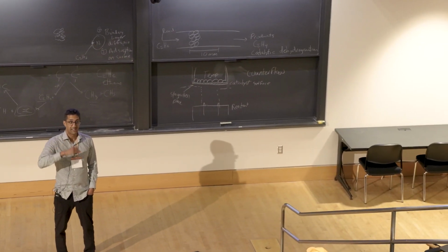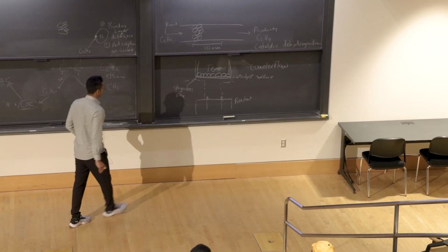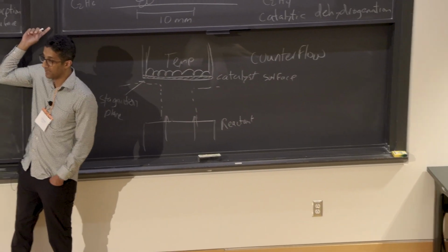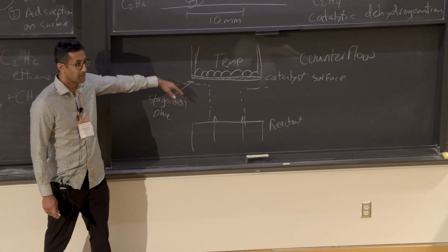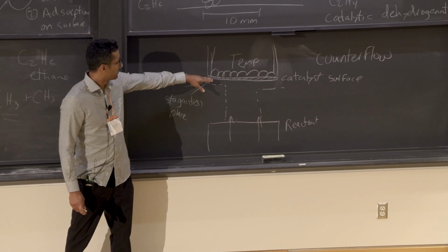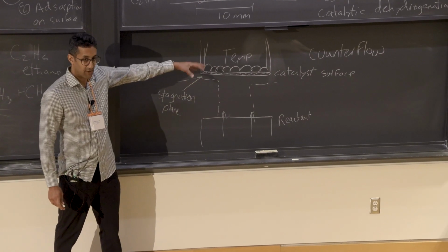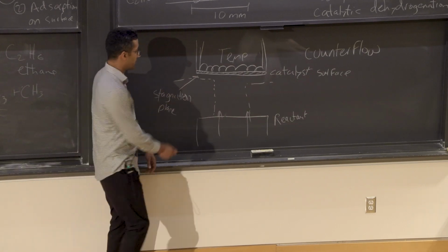And then you can calculate exactly the diffusion of the species, the reactant, to the surface of the catalyst. So that boundary layer phenomenon, which is rather complicated in spherical particles in a packed bed, you can figure out exactly. You can calculate it. And then you can deal only with the kinetic processes like adsorption on the surface, reactions on the surface, and desorption. And again, here you can use a laser.